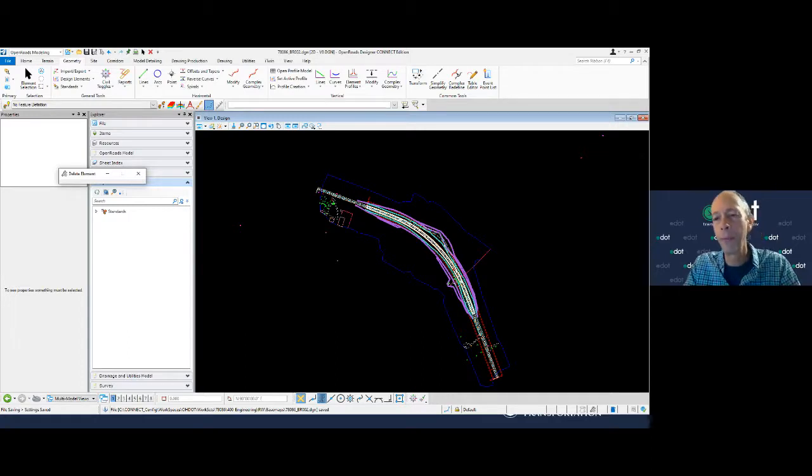So some of the survey and right-of-way personnel in their right-of-way file, so I've got a BR file open here, a base map for right-of-way. Some of them have been creating a survey field book in their right-of-way file so they can store survey points. And it's not necessarily what we're recommending, but it's working for them. And then some others are doing a geometry point and using those.